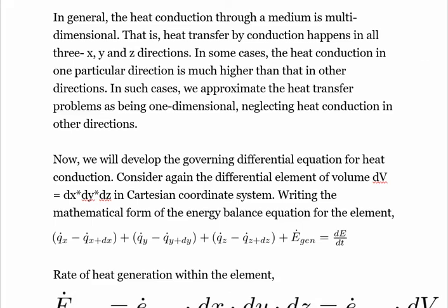In a similar way, in the direction of y, the heat entering from the y plane, that will be qy, minus the heat rejected from the y plane, that will be qy plus dy. And similarly in the z direction, plus the energy or heat generated is equal to the change of energy with respect to time.